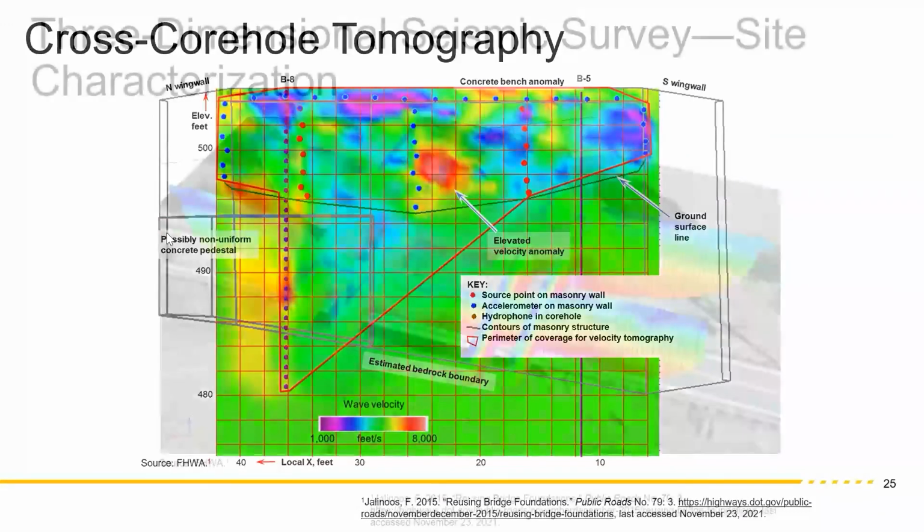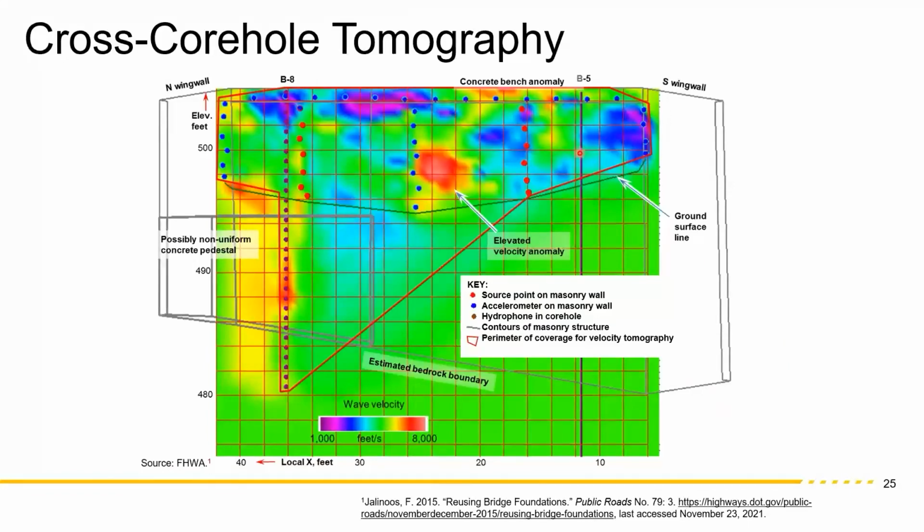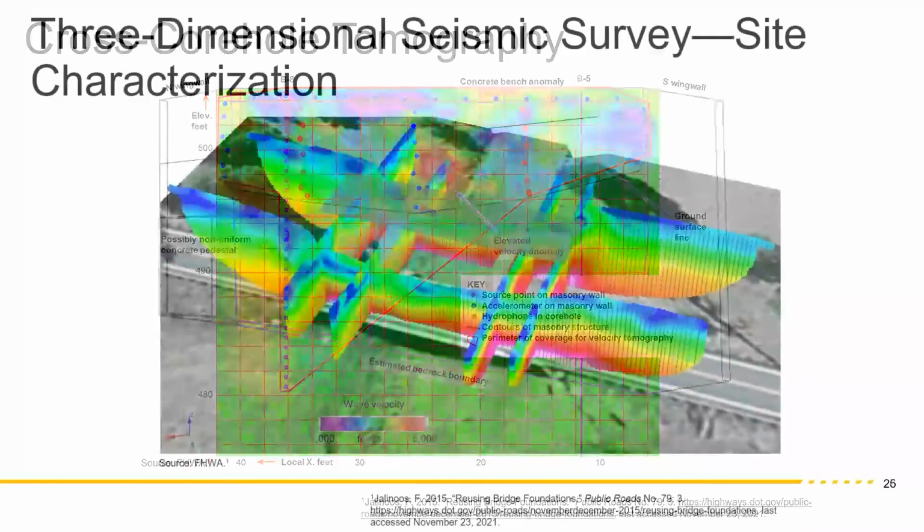Okay. Of course, if you have a pair of core holes, you can do cross core hole measurements. But here you need to have this, just like that cross-hole sonic logging that Bernie showed. But here we're using the geophysical, because of the distance involved, we use hydrophones and seismic sources, and then use many different angles rather than just looking straight across. For every source, we have many different angles, and you can do this tomographic imaging of the whole of the foundation, including the bedrock. And these were with the issues were with those holes that subsequently our Federal Land Office routed in.